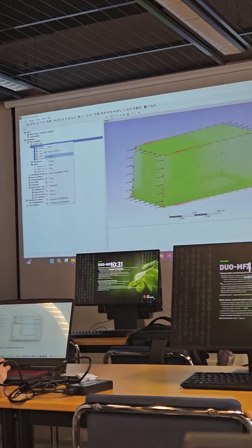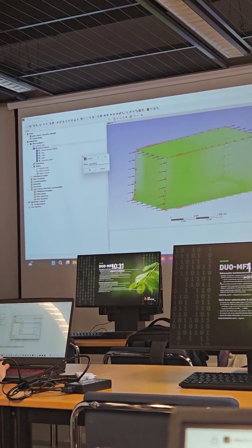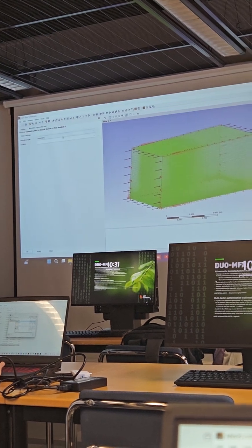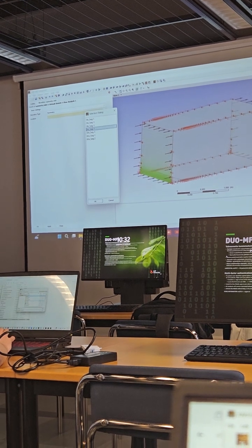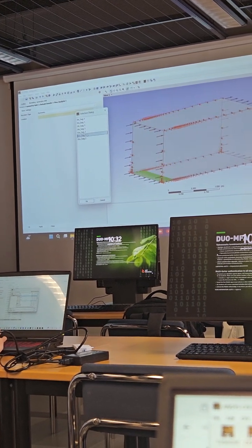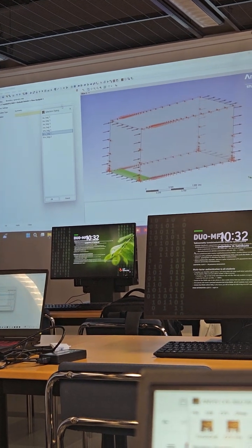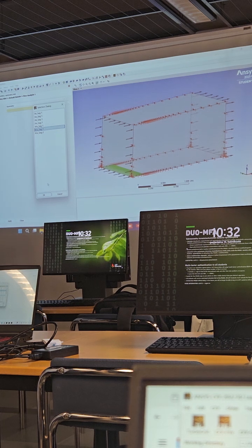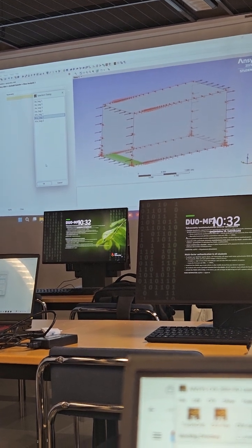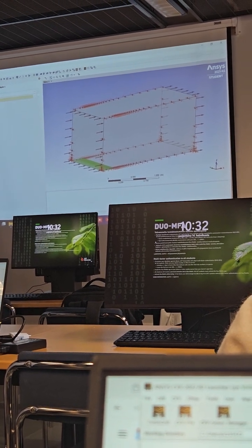And then we can set the symmetry at the inlet. This is this small surface at the inlet that we said doesn't affect the flow. So we can set it like a symmetry, or like in Fluent we will do as a slip wall. So no shear stresses on the flow.